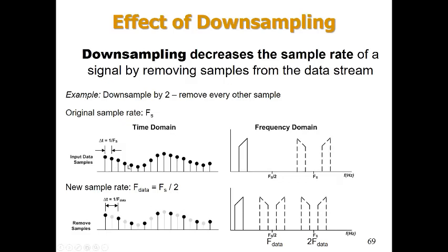And if we start off with an appropriate kind of signal and the right kind of sampling rates, in this case, this looks like it's actually worked out okay. Here's my new sampling rate. So we go to the new sampling rate over 2 to find its Nyquist rate. The original signal doesn't have any information above that Nyquist rate. This is just the spectral copy. And if we go through reconstruction and throw away everything outside of f data over 2, we're fine.